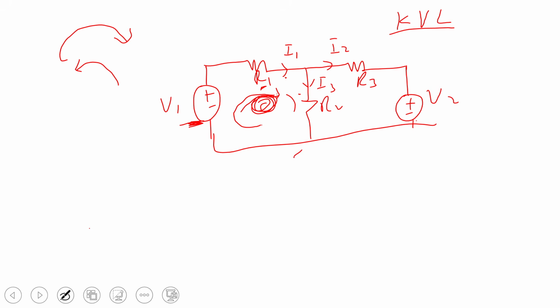So according to the Kirchhoff voltage law, put all the voltage sources at one side and all the current times resistor terms at the other side. In putting the voltages at one side, one thing you always have to make sure of is that anytime you are leaving the positive terminal, you make the voltage source positive, right? This time, going in the clockwise direction, I'm leaving the positive terminal. So I'll say V1 is equal to, since that's the only voltage source within the circuit, I put it at one side, and it should be equal to the current times resistor here, which is I1 R1.